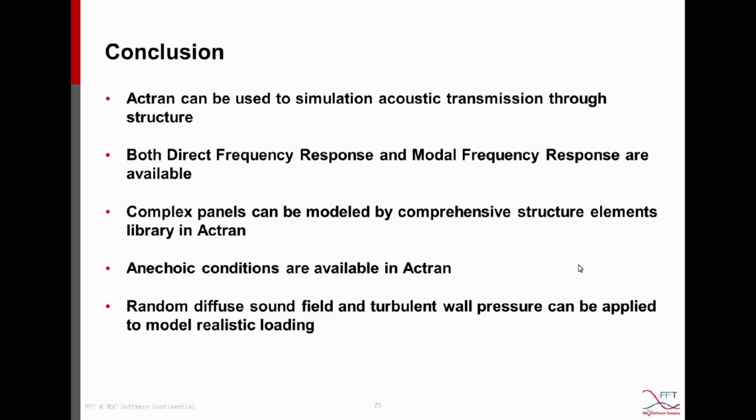Now to conclude, we have seen that Actran can be used to simulate acoustic transmission, or in other words, acoustic insulation of structures. So both direct frequency response and modal frequency response are available for different purposes. Modal frequency response is suitable for lightly damped structures, and direct frequency response is more suitable for highly damped, complex damping and porous material.